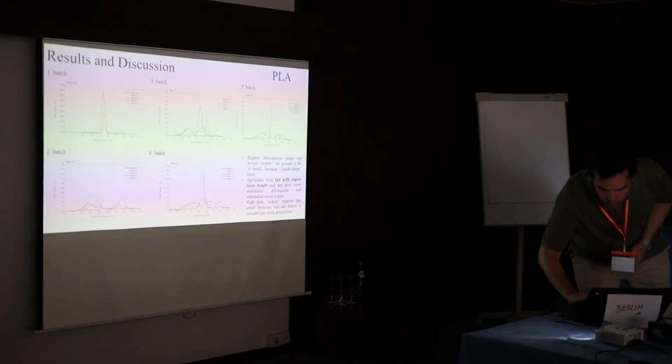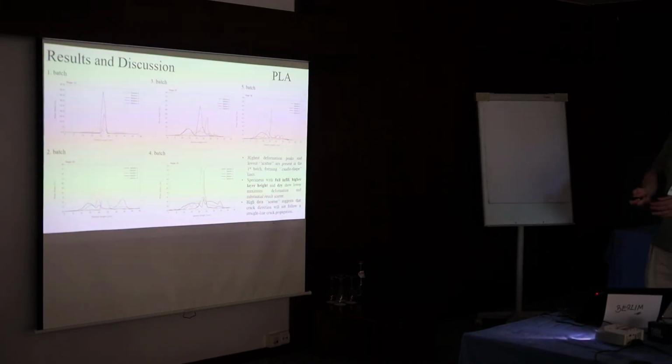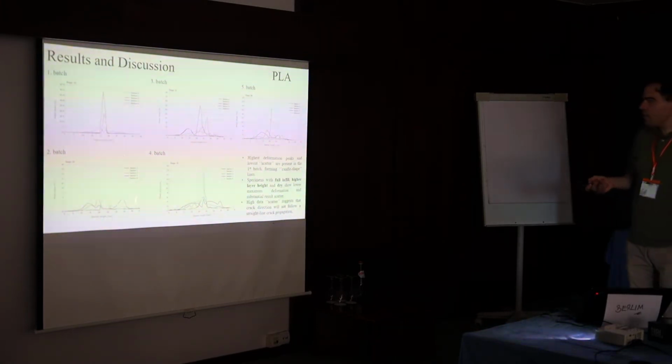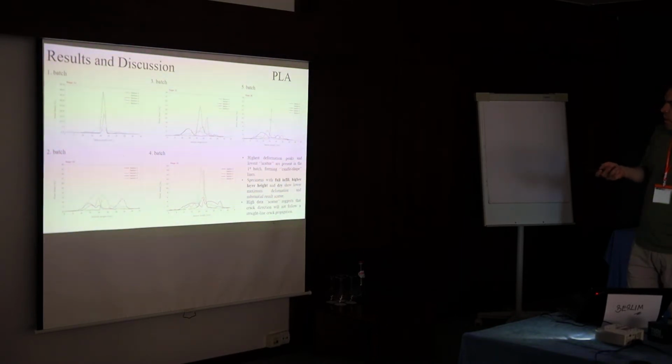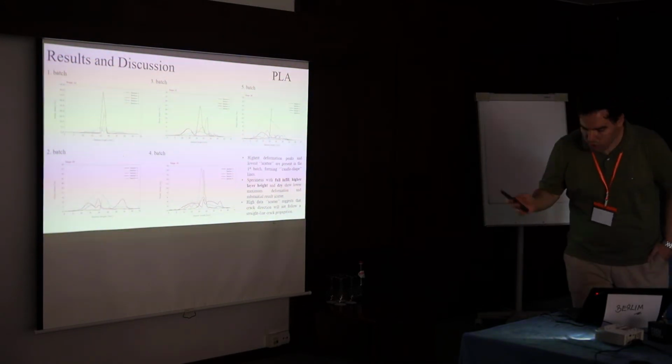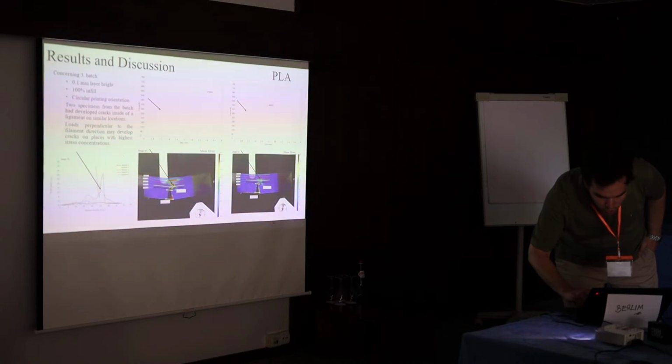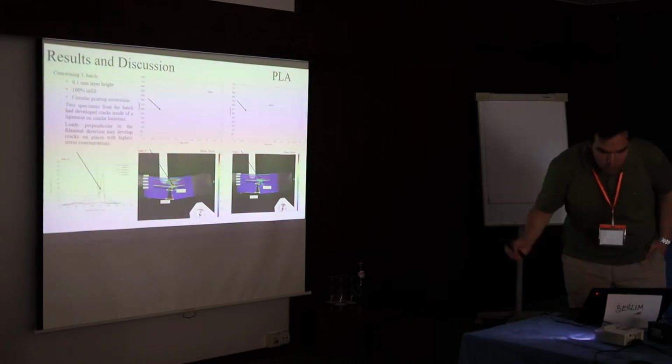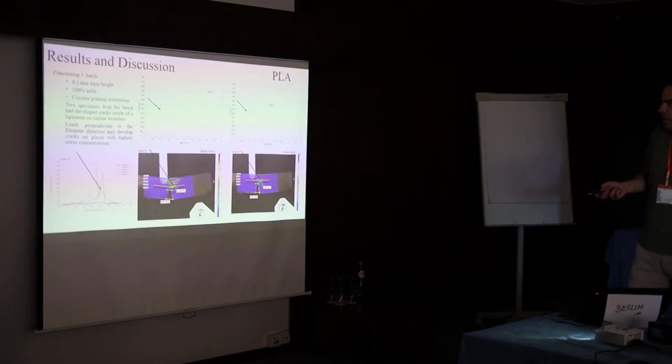This is the one. So here we have higher value scatter on the left and on the right hand side. The best results according to the straight crack propagation path will be in the batch with 50% infill density and 0.1, so the lowest layer height. Also in some full infill density batches where the direction of printing was perpendicular to the printing direction, we also